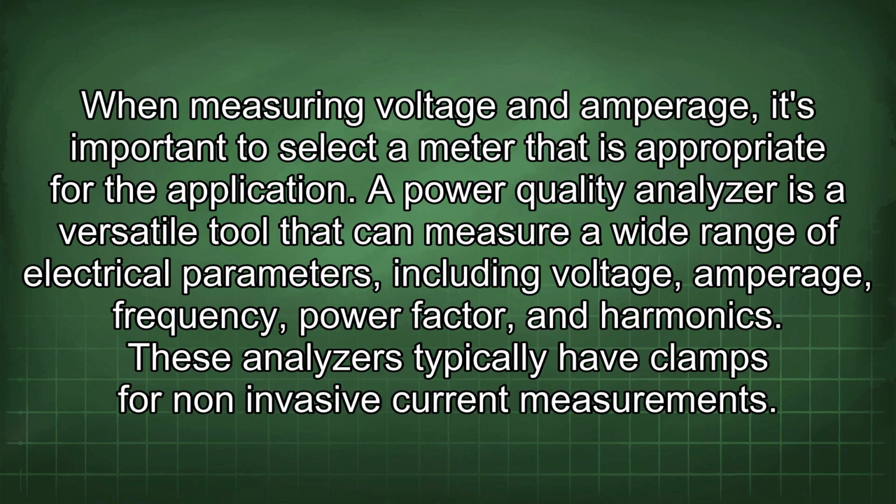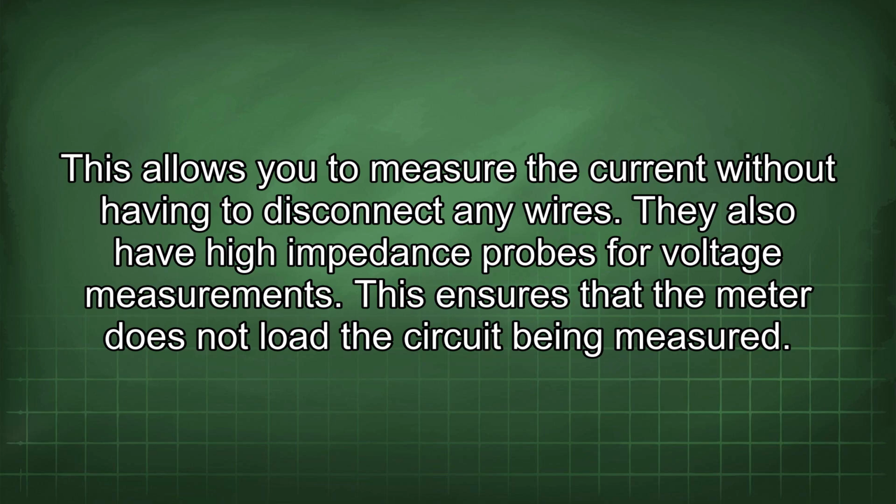When measuring voltage and amperage, it's important to select a meter that is appropriate for the application. A power quality analyzer is a versatile tool that can measure a wide range of electrical parameters, including voltage, amperage, frequency, power factor, and harmonics. These analyzers typically have clamps for non-invasive current measurements. This allows you to measure the current without having to disconnect any wires. They also have high impedance probes for voltage measurements. This ensures that the meter does not load the circuit being measured.